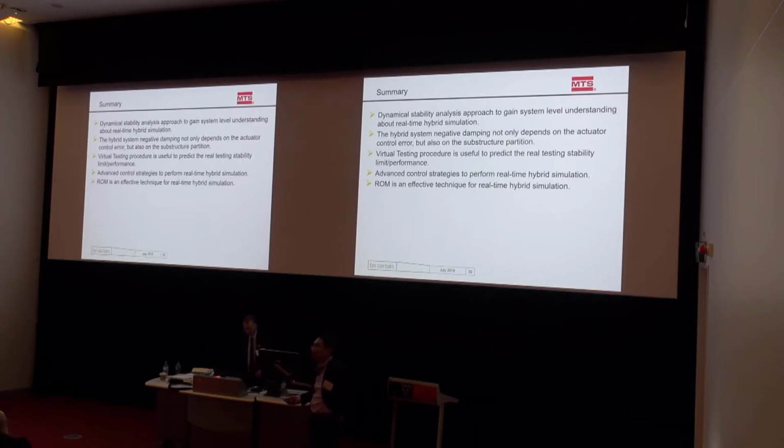Is this reduced order based on which method? The conventional method of model reduction, or? The reduced order model? It's actually just based on modal analysis. Like you do a FEA, in any FEA you can do a modal analysis, right? Then you use the eigenvalues and eigenvectors, and you can reconstruct that reduced order model.